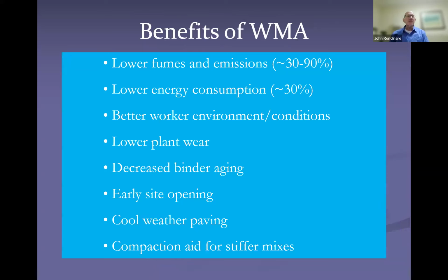So benefits of warm mix: lower fumes and emissions, lower energy consumption, much better worker environment and worker conditions. You're not getting the fumes off that newly laid asphalt. You're not working in that real high temperature. It works out real well for both the agencies and the producers.